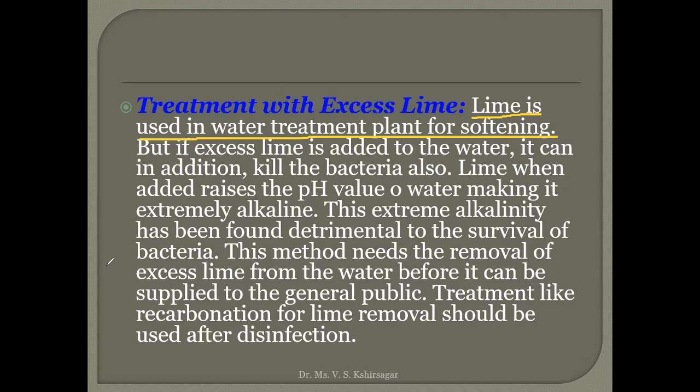But if you use excess amount of lime, then it will convert. Lime's nature? Alkaline nature. So because of that alkaline nature, that excess quantity of lime will convert that water into alkaline nature. And in the highest alkaline level of water, the bacteria will not survive. Okay, so it will be found detrimental to the survival of bacteria. They will not survive, and because of that they get killed. Okay, so this way disinfection is possible by using the excess lime.